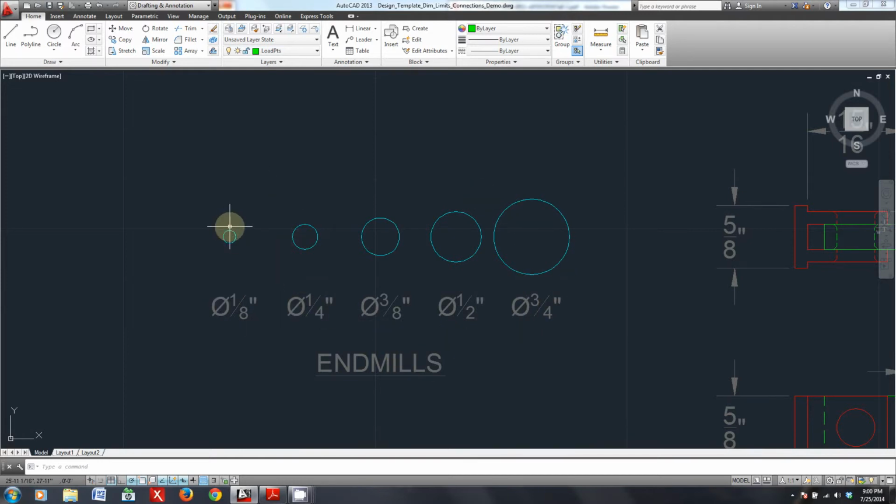So starting from the smallest, I did at one point use 1/8 inch end mills, but I highly regretted it, and I would highly advise that you don't pursue any designs that make use of 1/8 inch end mills, because you will be losing a lot of money doing it. So try to avoid it.